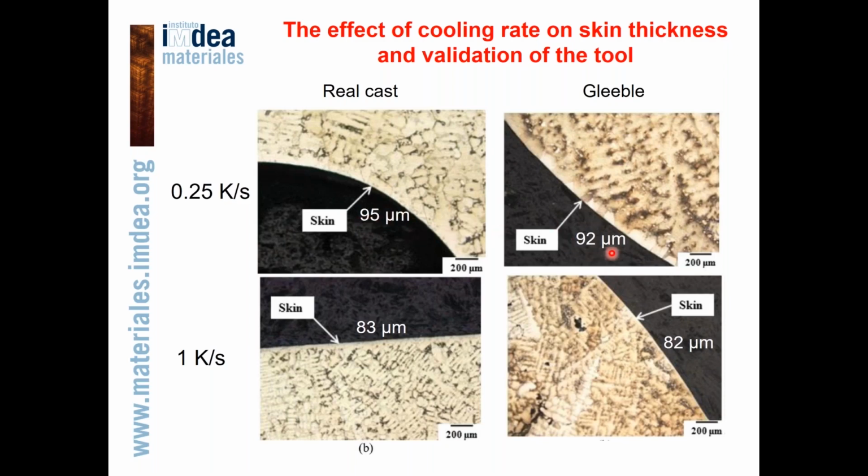We have 95 and 92 microns. With increasing cooling rate, the thickness of the skin somewhat decreases, and again, this decrease is also well reproduced by Gleeble.